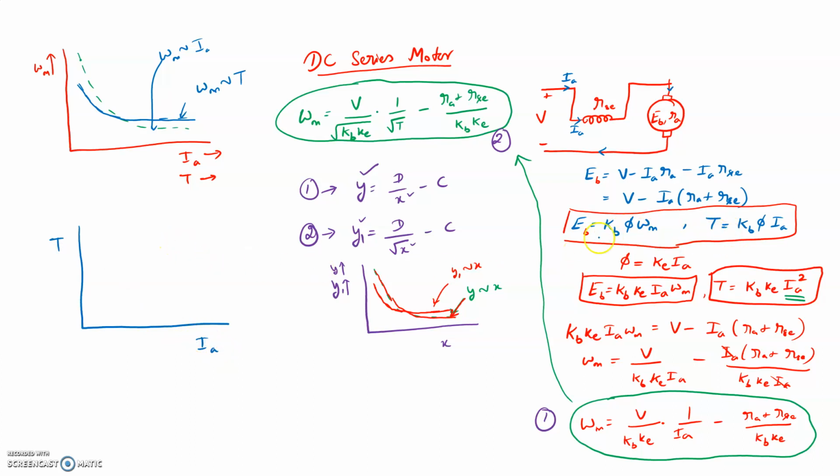Usually, for how the torque varies with the current, there are two expressions. One is, we know that T is equal to K phi into IA. And another one is T is equal to K and IA square. So there is one expression where T is proportional to IA square. If the flux is constant, we were not going to use this. But the importance of writing it here is that, let us see.